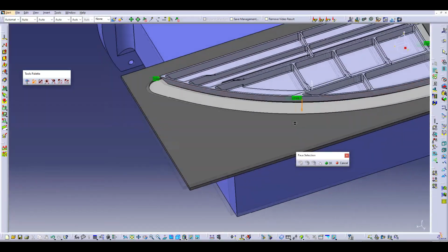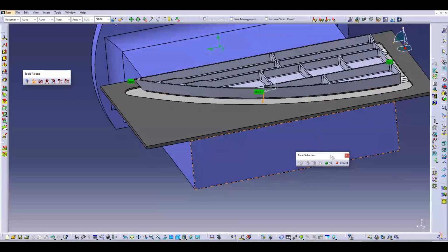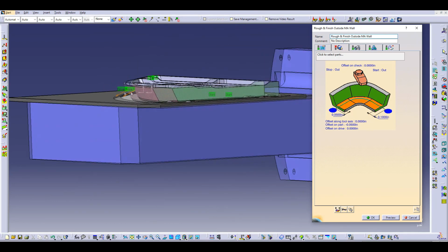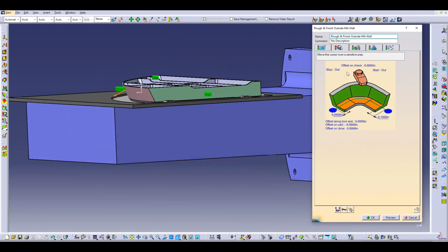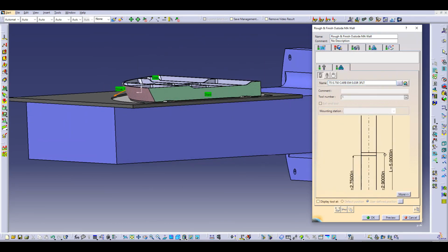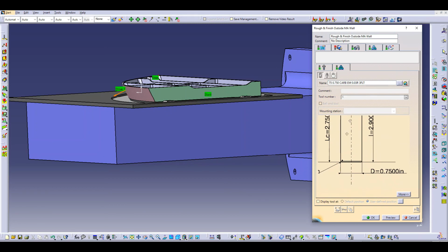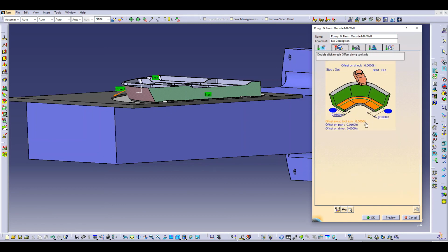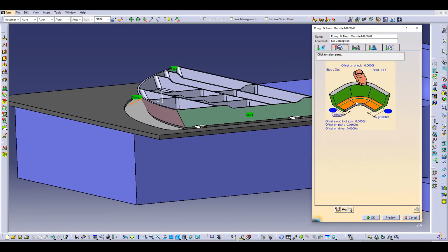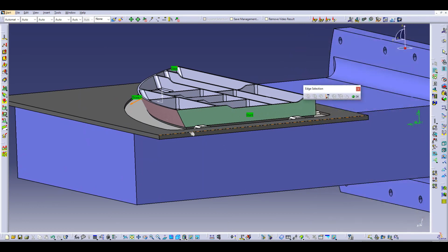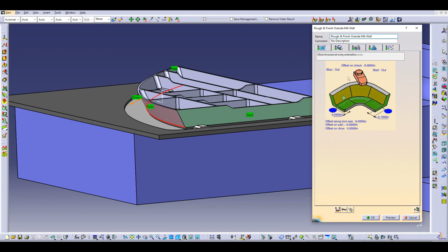And then instead of selecting this channel here as my bottom, if you do that, since you're canted and you're cutting under that, depending upon your radius, let's just take a look at our tool here, you could end up actually having your radius up on the wall. I'm going to show you something on that. So instead of doing it that way, I'm going to right click on this and say use curves as part. So I'll select that. That now makes that curve the part surface.